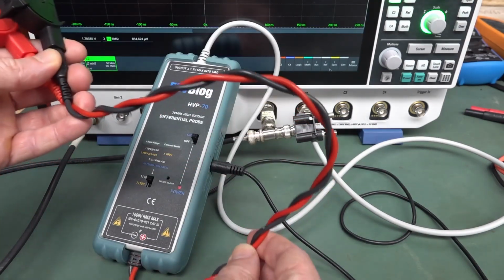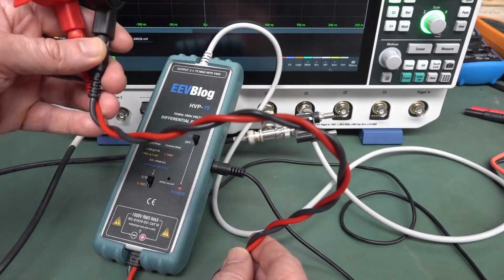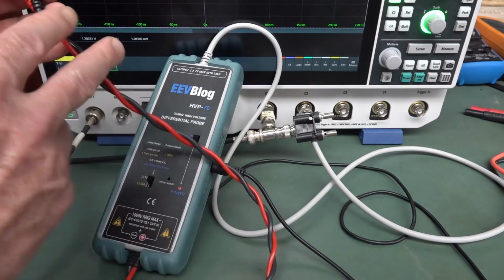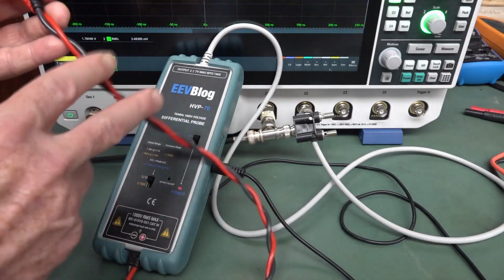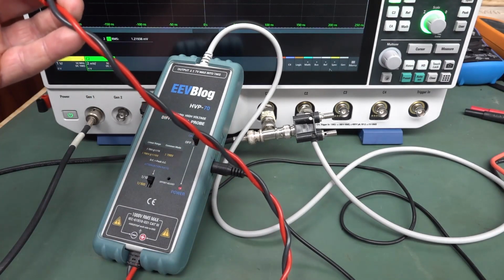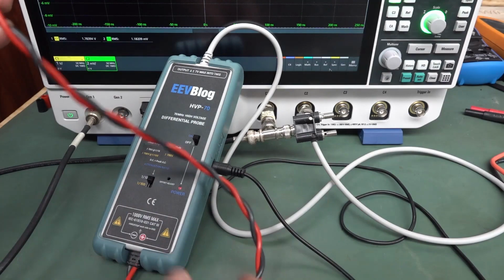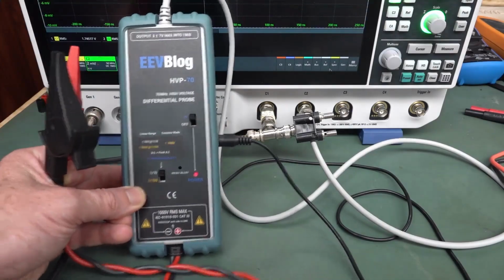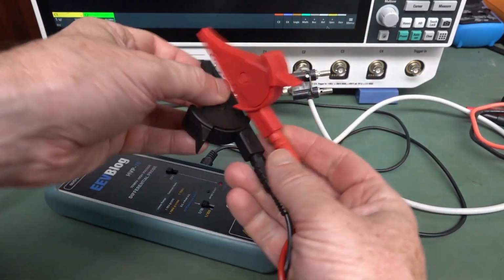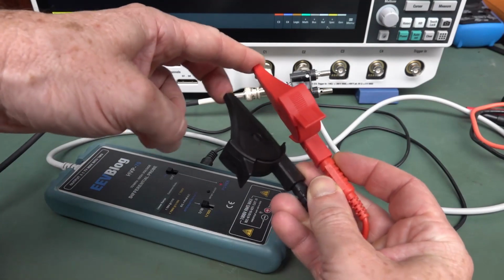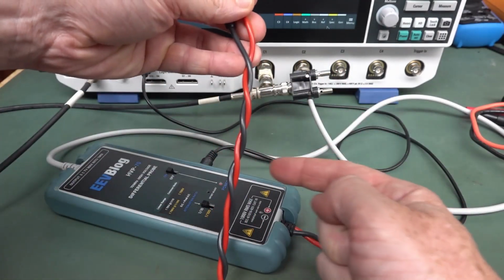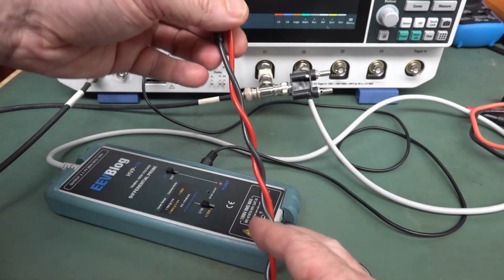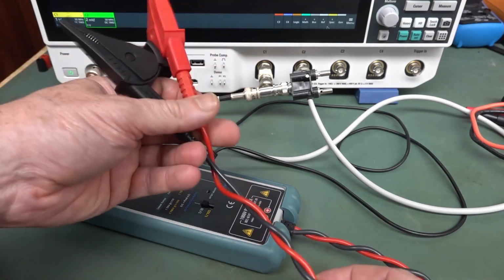And this is why the wires are twisted like this. If you're measuring a differential signal, any external noise or interference should, in theory, apply to both wires at the same time. So it's an external reference, in this particular case, reference to the grounded output of our differential probe. So the job of a differential amplifier is to amplify the difference between its positive and negative input while rejecting all of the signal, or as much of the signal as it can, that is applied commonly to both of these wires. So that's why it's a common mode rejection ratio.